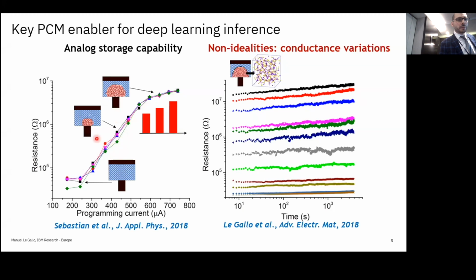So I don't think this is as reliable in ReRAM as far as I know, because it's pretty hard, I think, to program all these intermediate states in ReRAM. We have this filamentary conduction mechanism, where it's very hard to control the width of that filament. So you can do multi-level programming, but in my opinion, it's much more difficult with ReRAM than with PCM, where we are essentially modulating a volume. This is much easier to achieve, and reliable multi-level storage is much better with PCM. That is one of the strengths of these PCM devices: multi-level storage can be achieved very reliably.